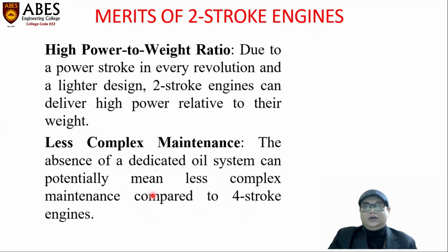High power-to-weight ratio. Due to a power stroke in every revolution and a lighter design, two-stroke engines can deliver high power relative to their weight. Next is less complex maintenance. The absence of a dedicated oil system can potentially mean less complex maintenance compared to a four-stroke engine.